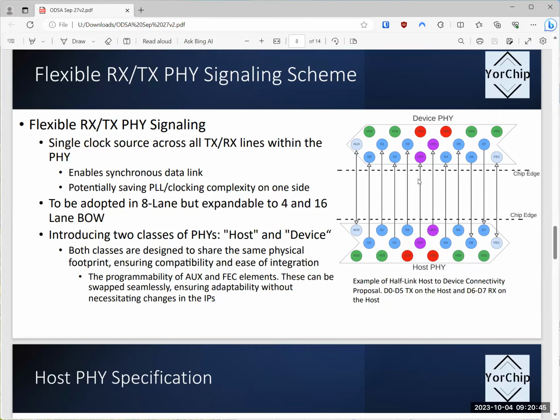Yeah, please go ahead. The other thing is that because you have this special mode, your clock is a shifted half cycle, right? In my sign-off stage, in my timing sign-off, I also have to assume that if I shift half cycles forward on the data skew and so on, do I have enough margin compared to those default modes where I just care about skew?